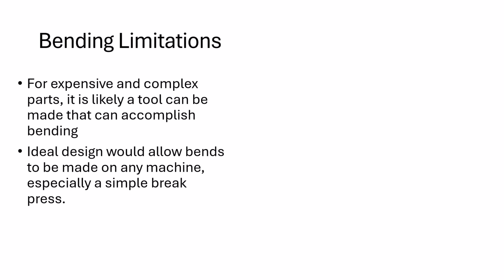This is just a general rule you should be following for all manufacturing processes: when you're designing something, you want it to be able to be made in as many shops as possible. You do not want to limit the method of manufacturing. All right, if I were to come up with a sheet metal design that was so complex, there's only one shop in the world that is even willing to make it, and it costs $1 million in tooling. Well, now if that shop goes out of business or they change their mind and say, I don't want to do it anymore, my design is over.